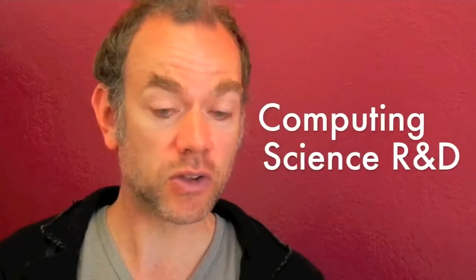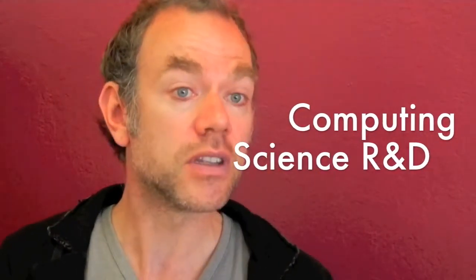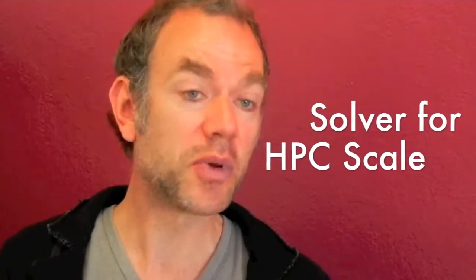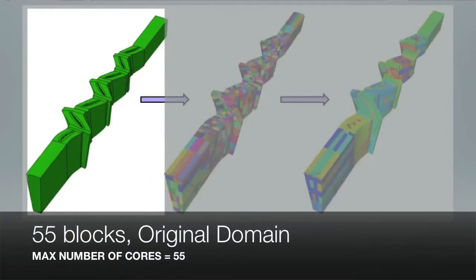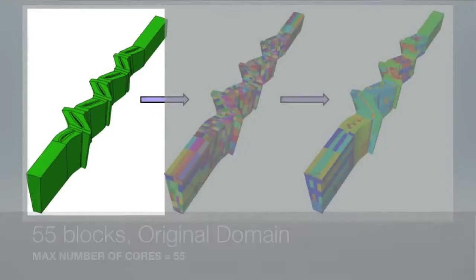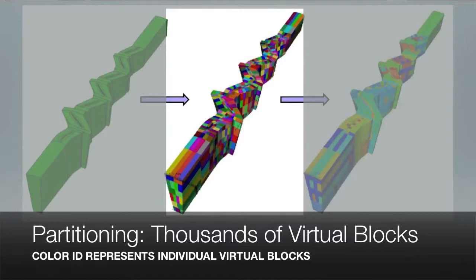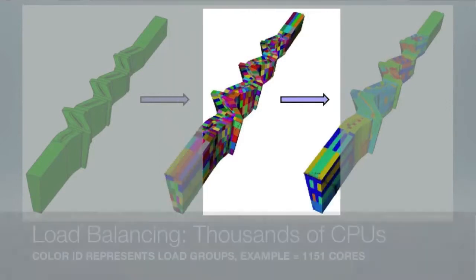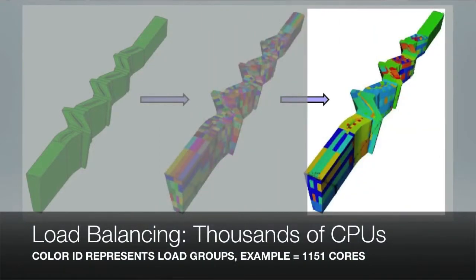All have tight schedules so the amount of analysis we can perform within a certain time frame is very important. The solver speed aspect is something on which we always insisted a lot in Fine Turbo, and the tool is now extremely competitive on that aspect. This includes fully transparent procedures to partition multi-block structure grids so that they may be easily distributed across thousands of cores while maintaining an optimal load balance.